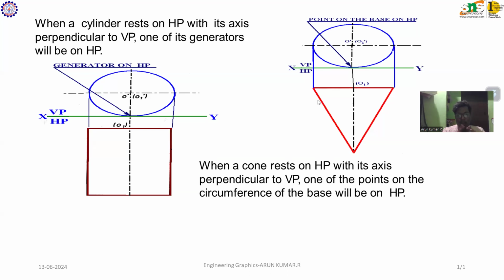So I have to draw the circle over here with a center point, and give the names 1, 2, 3, 4, 5, 6, 7, 8. I always use 8 equal parts because it is more convenient to solve circle problems. Four parts is also easy, but the accuracy of the sum is quite difficult. So once you complete the front view of the given solid, it's like a circle.